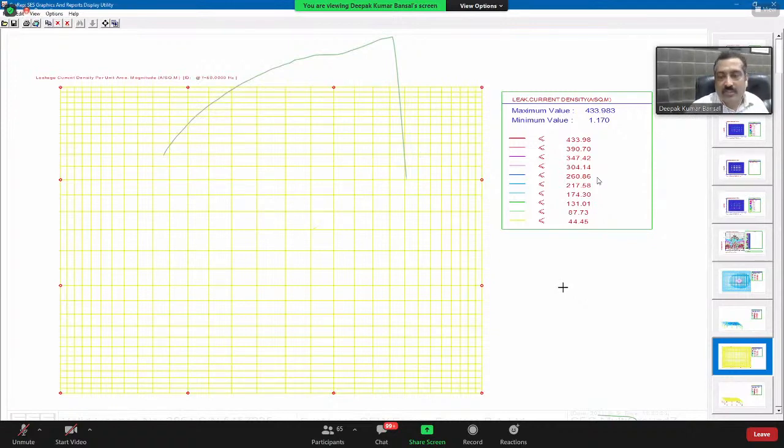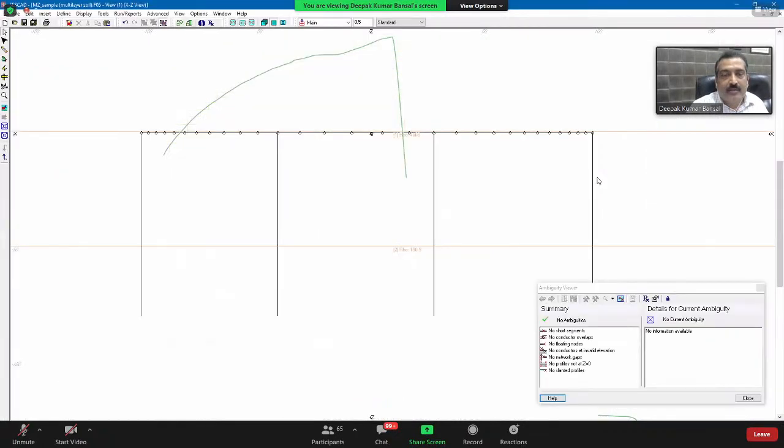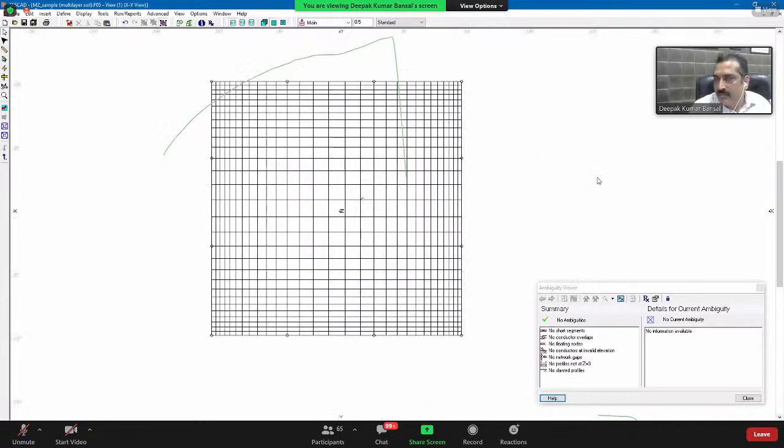As the soil resistivity starts increasing, the current distribution will change again, and it will form a loop basically, and it will keep on increasing soil resistivity, and the soil becomes more and more of an insulator because there will be no moisture after a few microseconds or seconds. There will be no moisture in the soil, and our grid will fail. So we should design the grid in such a way that these things remain under control.